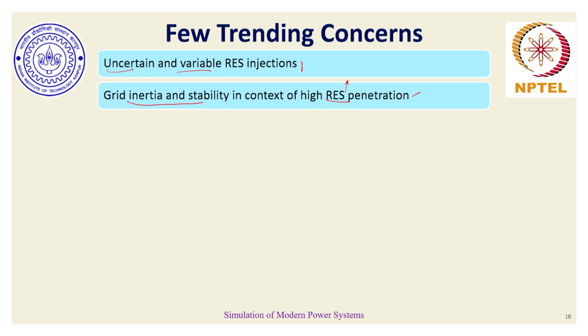resources such as solar power or battery storage, these devices do not have any rotating part among themselves, and hence the corresponding kinetic energy ratio has gone down, which in a way tends to bring down the grid inertia, and during disturbances this inertia plays a very important role. Basically, it gives a measure of how resilient the system is in case of disturbances.